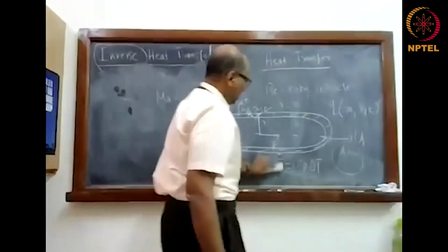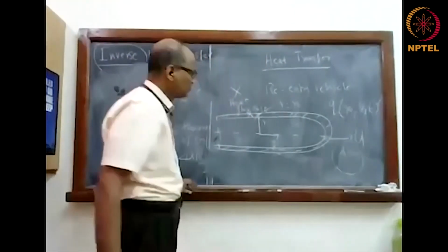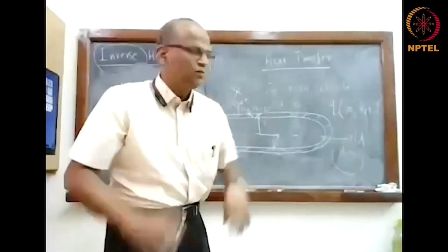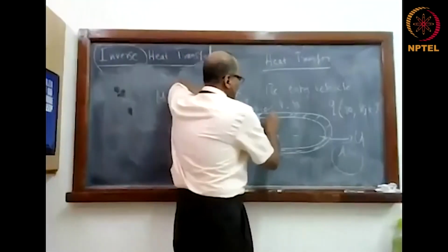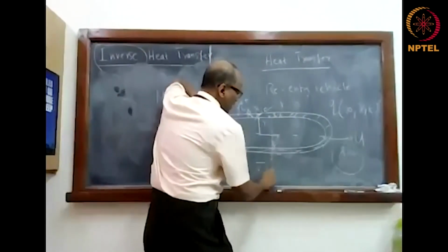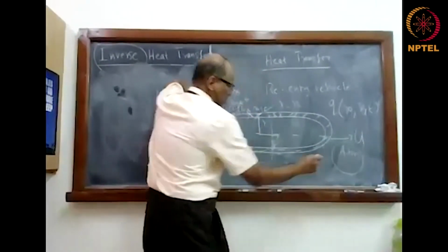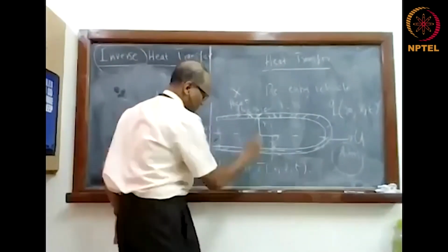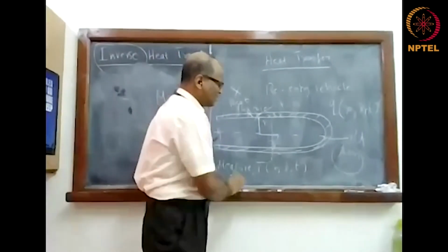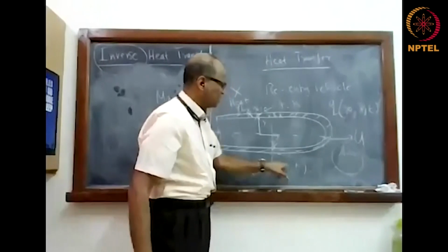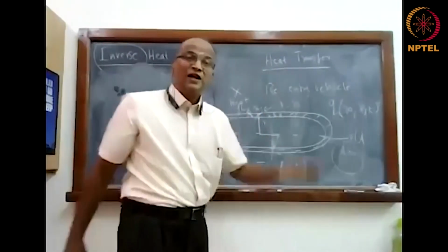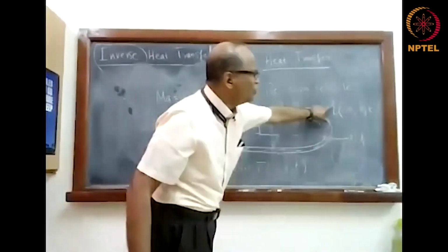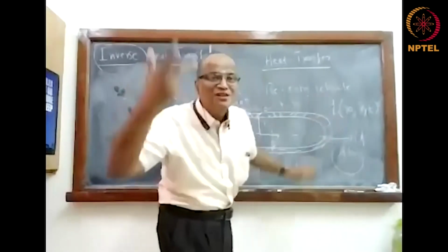So now the challenge is, can you tell what this is? It is not an easy problem to solve. So what they try to do was, they take some measurements. T of r, z and t, measure. Measure T of r, z at certain finite values of r, certain values of z at certain points in time. Have an unsteady heat conduction problem. Solve it with some assumed values of the function estimation. So this is the estimation problem.